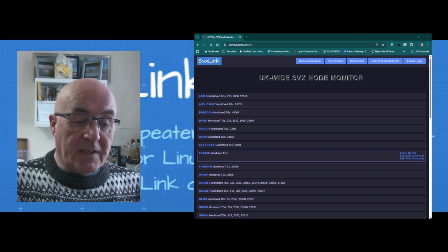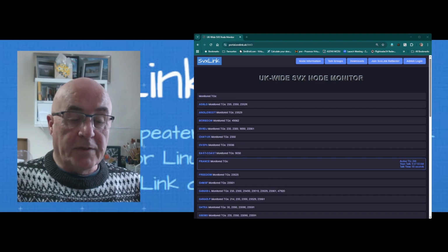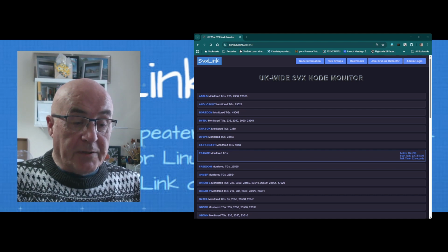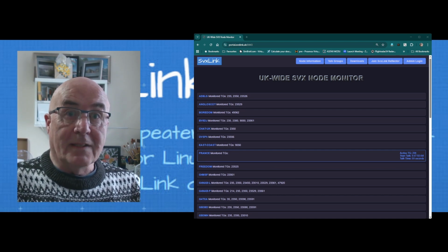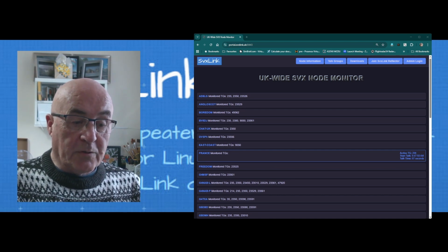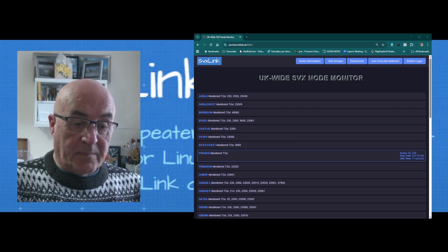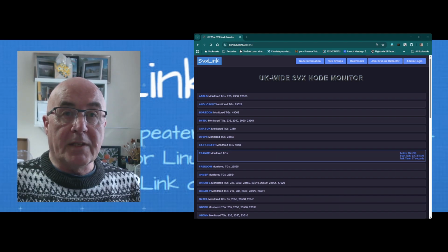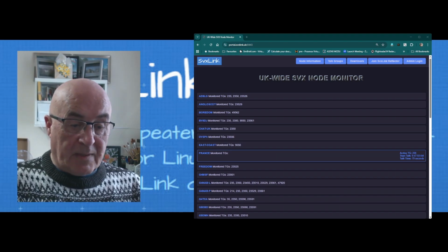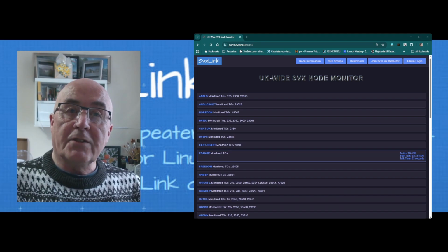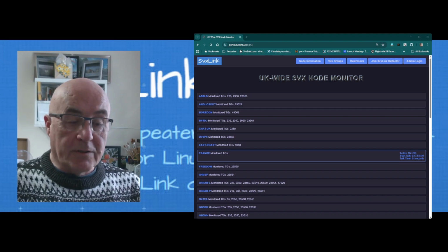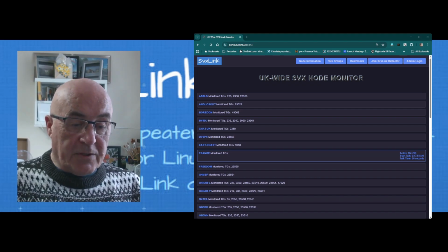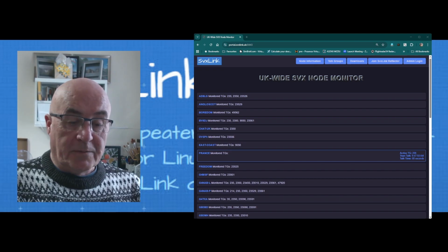If a user meets another and they decide to move off the 235 group, and sometimes this is conducted automatically, they go to another talk group, or in the case of the automatic shift, to a random talk group. The rest of the system will reset after 30 seconds to passive connectivity again, leaving it free for further communication. The two users continue their conversation in their newly assigned talk group, because the system announces the change of talk groups.